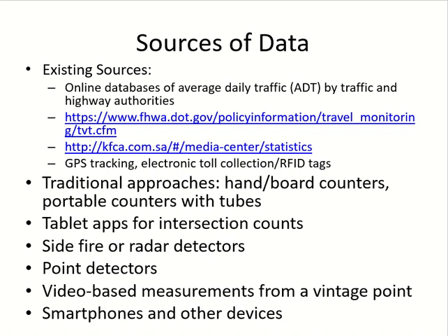Some of them are point detectors. Point detectors are installed under the road, under the pavement. So they detect the car when it passes over them. But again, they are installed and you don't need to go there again and again.